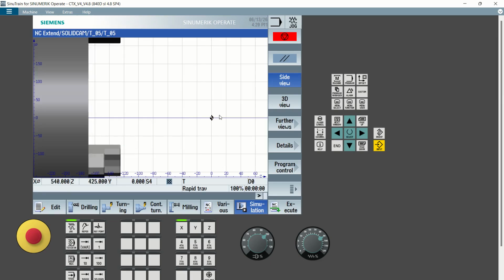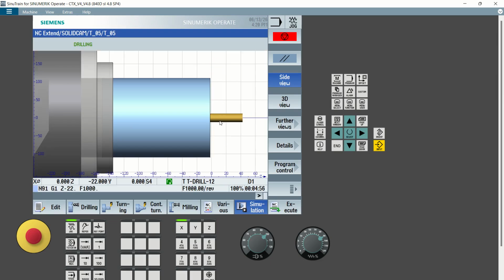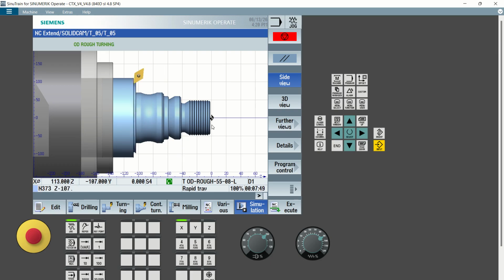This is how programmers do. So you need to understand errors in your program. When you refine these errors, now you take the program to the actual machine, and this is what we do at 5-axis precision academy. You're able to fine-tune all the program from the design. You go to your CAM, fine-tune the program in the CAM, then take the code. Once you simulate it, now take the code. When it's okay, now take the G code to your machine. And this is what CNC are doing with DMG Mori machines, advanced machines. Come to a center, you learn this.